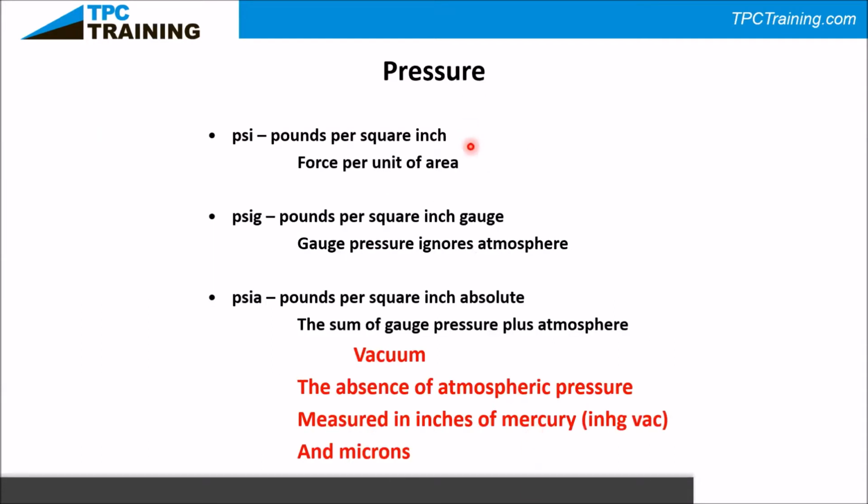Now, the way we measure pressure in air conditioning is PSIG. If you have a set of manifold gauges, which is like a stethoscope where you can look inside the system and see what your pressures are, you take that pressure and we can say at this pressure, this refrigerant is this temperature. What they're doing is subtracting off the atmosphere.